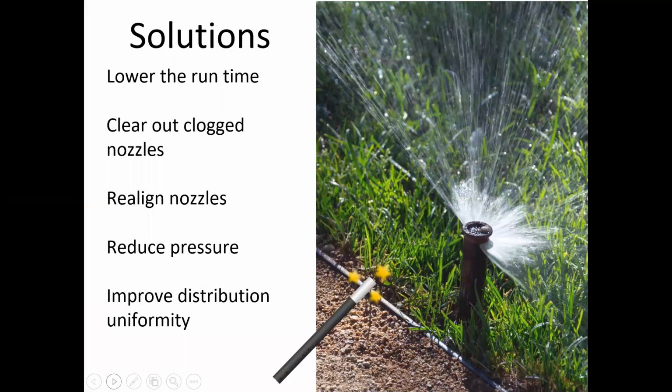And one example is to see when the runoff is occurring. If I have a lawn on sprinklers, I'm running that for 10 minutes and I see that within 7 minutes there's runoff, I might decide to change those into multiple cycles of 5-minute sessions so that the soil can actually absorb the water, and my lawn can still get the benefit of the same amount of water that it needs to survive.